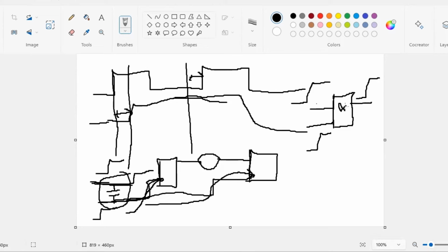AND gate delay is calculated based on input tran and output capacitance load. This AND gate will be placed in my design, so how much is the output capacitance? Based on those values, it takes the cell delay from the library .lib file.